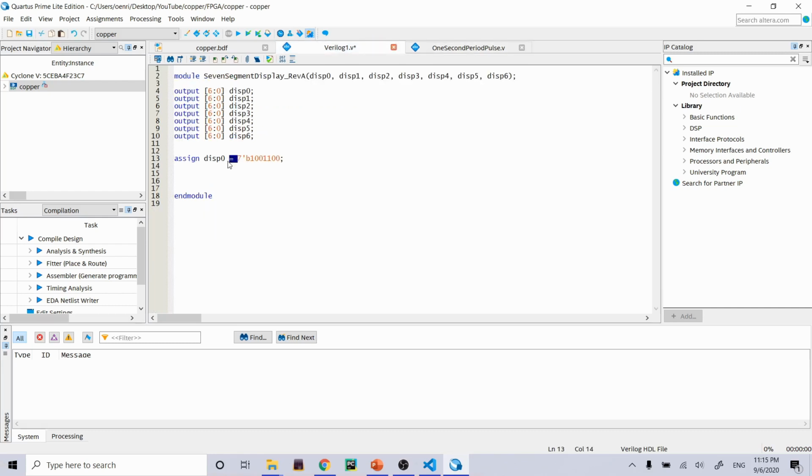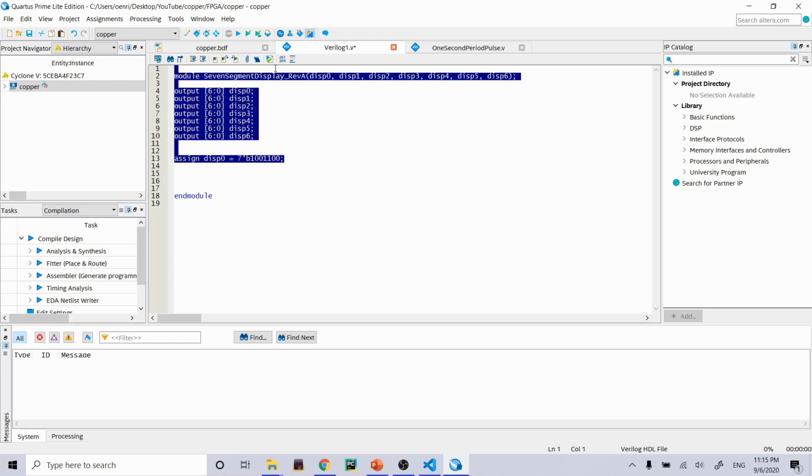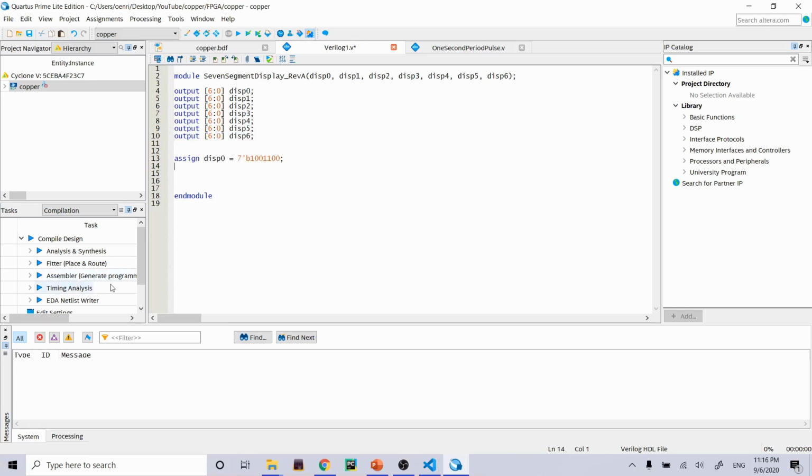Whereas this one, just an assignment operator without the less than, is in constant flux. This value that's being written out to this left hand side is never going to be a guaranteed value for a certain amount of time. It could change at any point in time. The significance of that will be much more clear as modules get more complicated and timing actually becomes an issue. To our credit, timing has not been an issue because 50 megahertz is relatively slow and we are working with relatively small logic. We will have to talk about it eventually in the future. Right now we don't have to talk about timing. We just have to understand that that's the difference between these assignment operators.